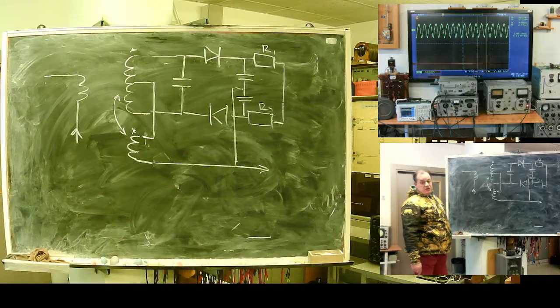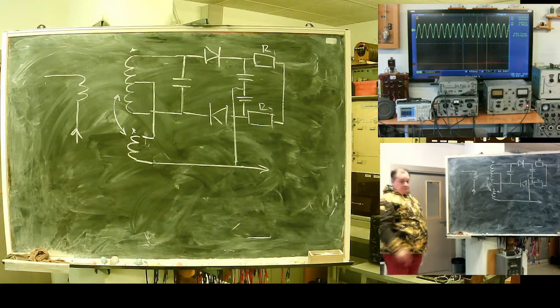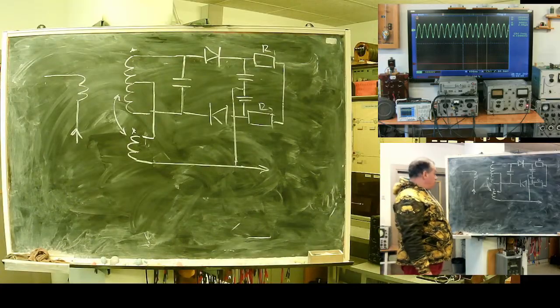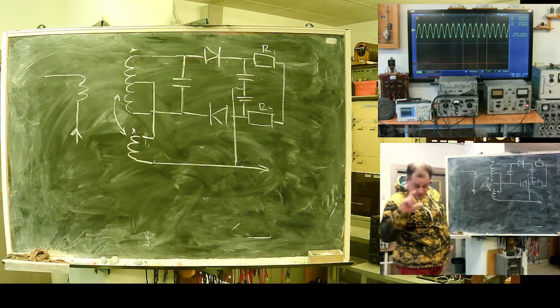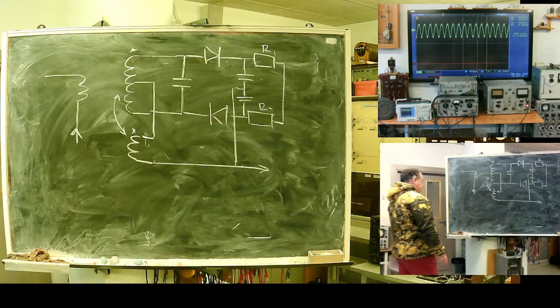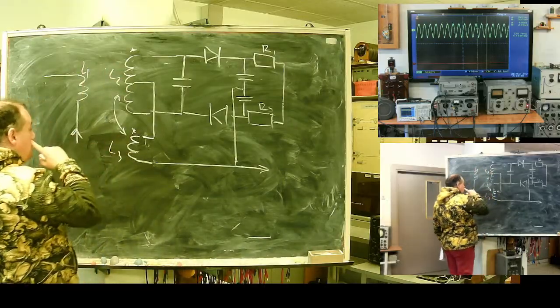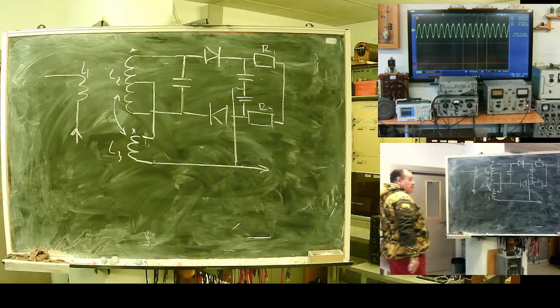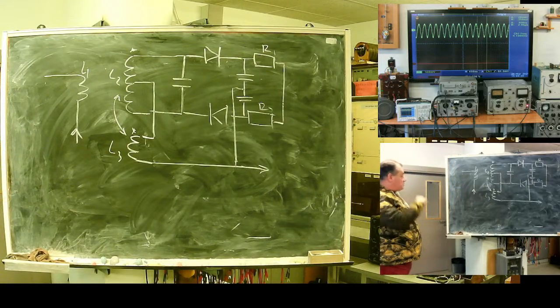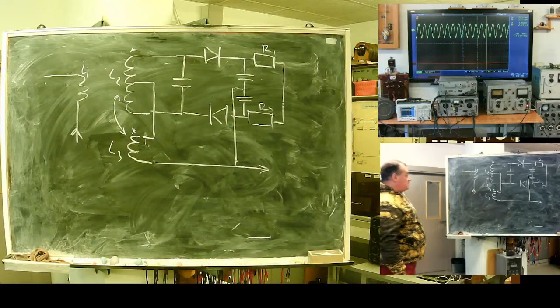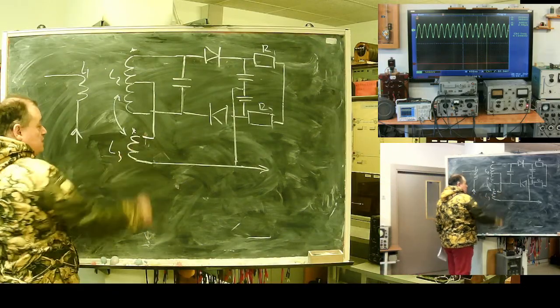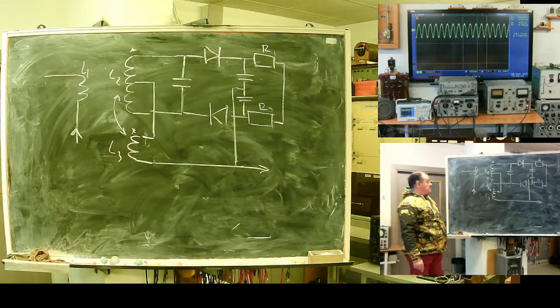In case the frequency shifts, the system is no longer balanced and there will be a voltage difference at the load resistors, which can be taken from this pair of capacitors. One moment: to suppress parasitic amplitude modulation, this coil is used. It compensates in case we have parasitic amplitude modulation.